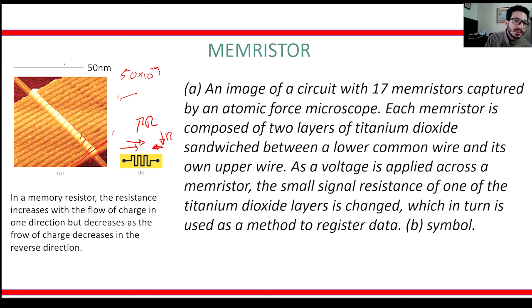direction. Because you know, in a resistor, you can place the resistor any way. It's not polarized. Actually, some capacitors are like that too. When you have a resistor, at any point you could be positive or negative. It's just something that will impede the flow of current. But with our memristor, it's important to know what direction you're going to apply your current to go through. So you have to know which one is your polarized leg.